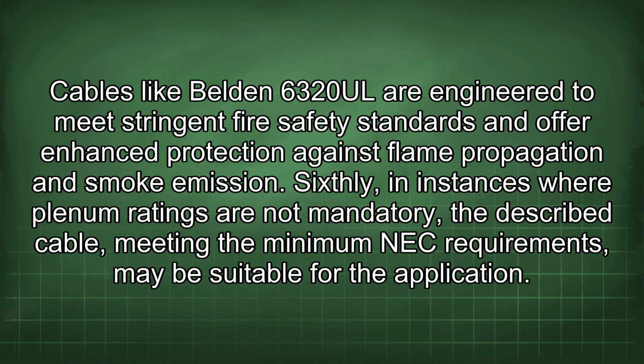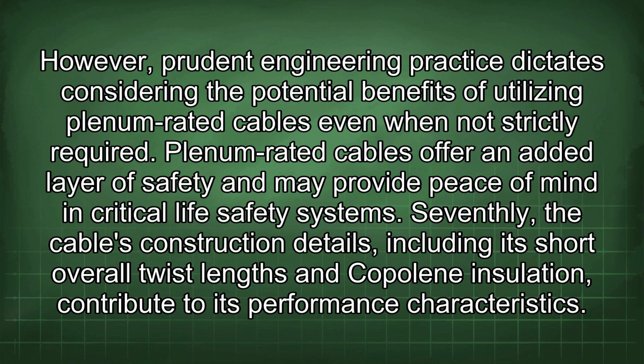Sixthly, in instances where plenum ratings are not mandatory, the described cable, meeting the minimum NEC requirements, may be suitable for the application. However, prudent engineering practice dictates considering the potential benefits of utilizing plenum-rated cables even where not strictly required. Plenum-rated cables offer an added layer of safety and may provide peace of mind in critical life safety systems.